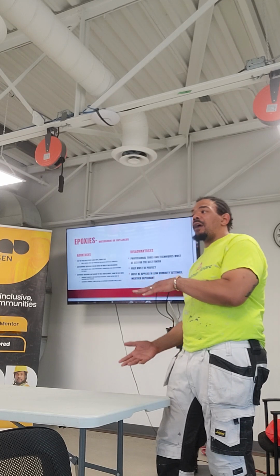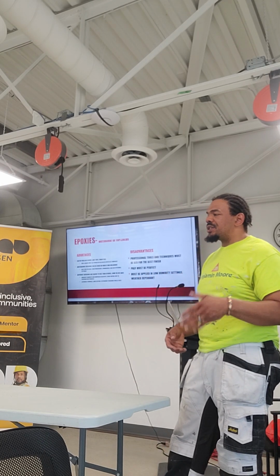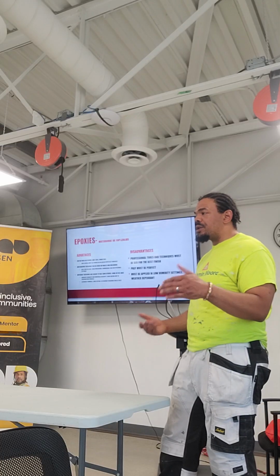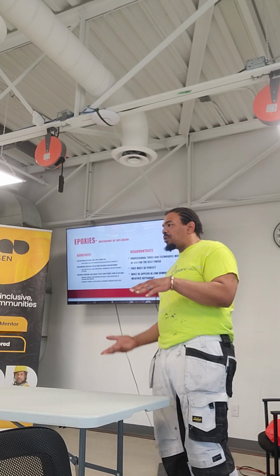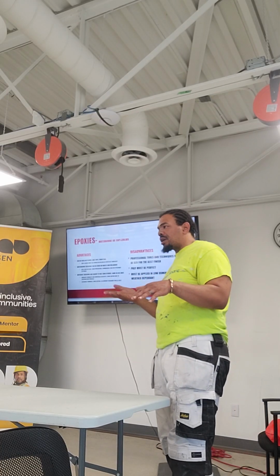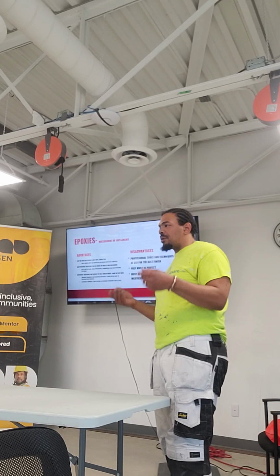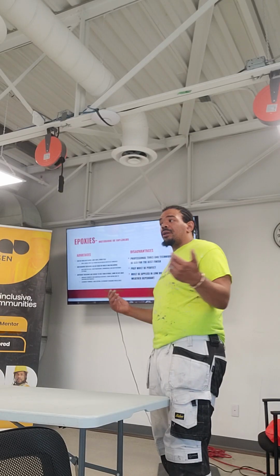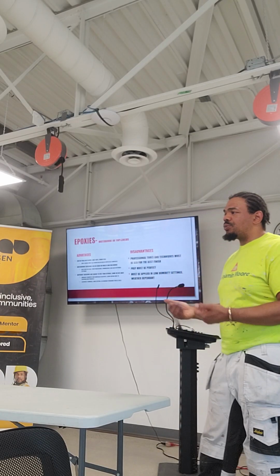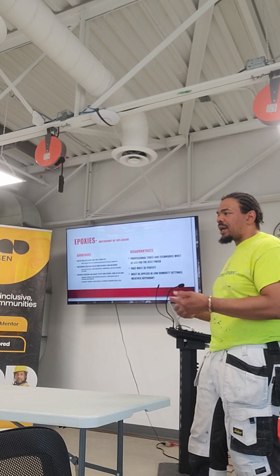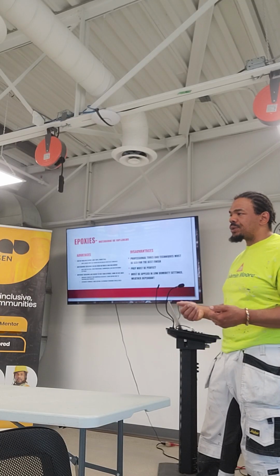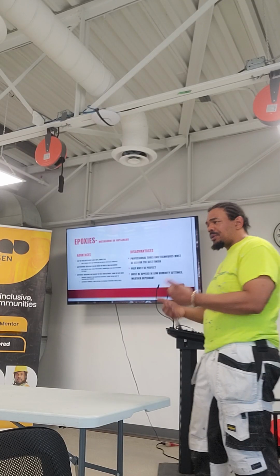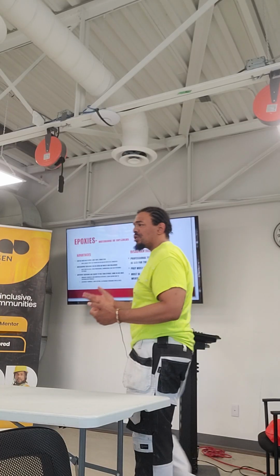Sometimes you have situations in basements in certain areas near water, or near a water shelf, where you can have moisture rise up out of the ground. The groundwater can come up and cause issues. That's how you get a lot of cracking and movement. But all of that is directed by the groundwater and how level and how dry the soil and sediment is underneath the house. That will produce some of the cracking if water is moving or if the soil is wet.